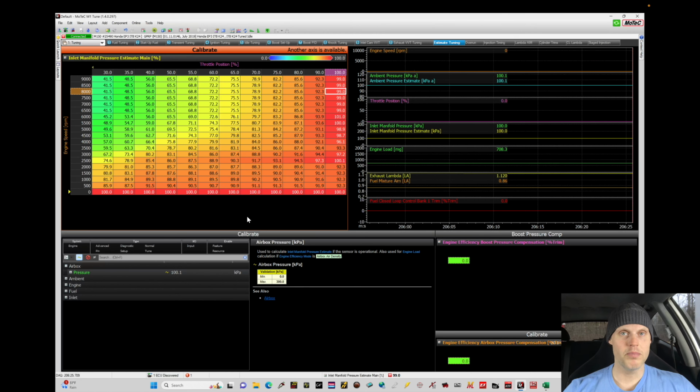Now, the one benefit that we have going for us is that we've done a lot of the calibration work in our low cam tuning tutorial. So meaning our spark timing is going to be relatively close to start off in our VTEC operation. We'll also find our fueling should be ballpark close. It's probably going to need a little bit more fuel. We'll deal with that in the estimate table. And the variable cam control is something that we do have to sort out in this training module. Let's jump in and take a look at what we have to set up and configure.